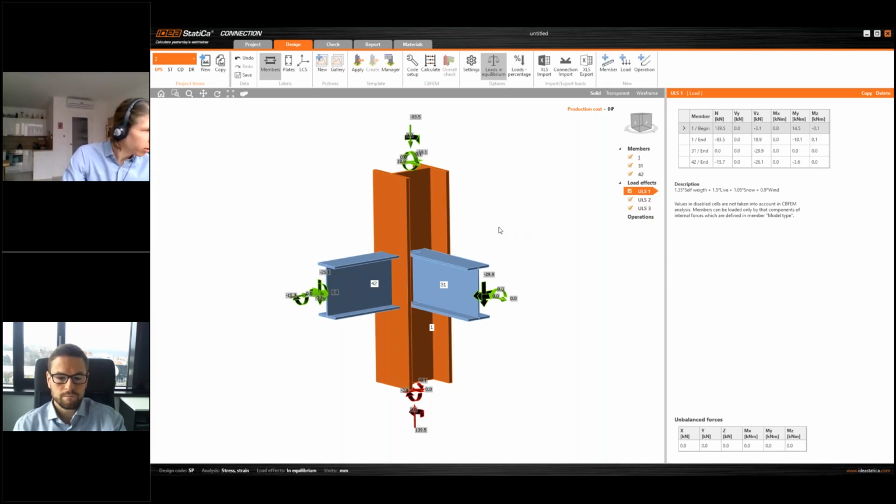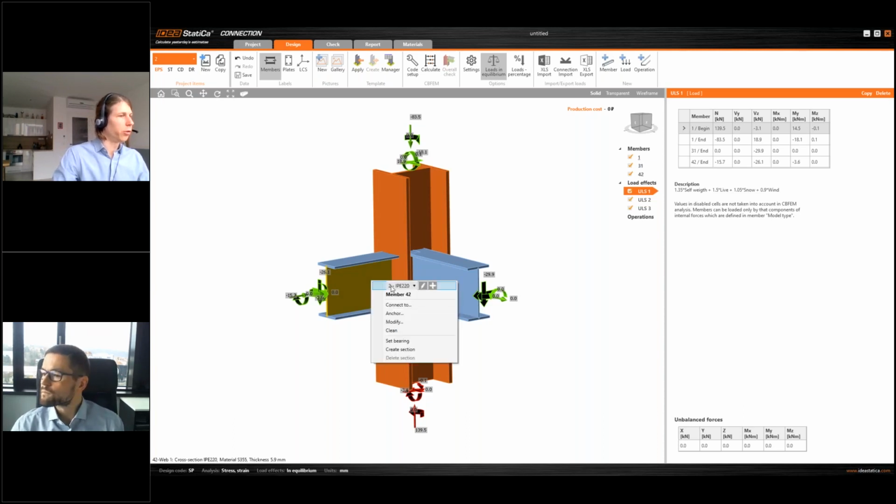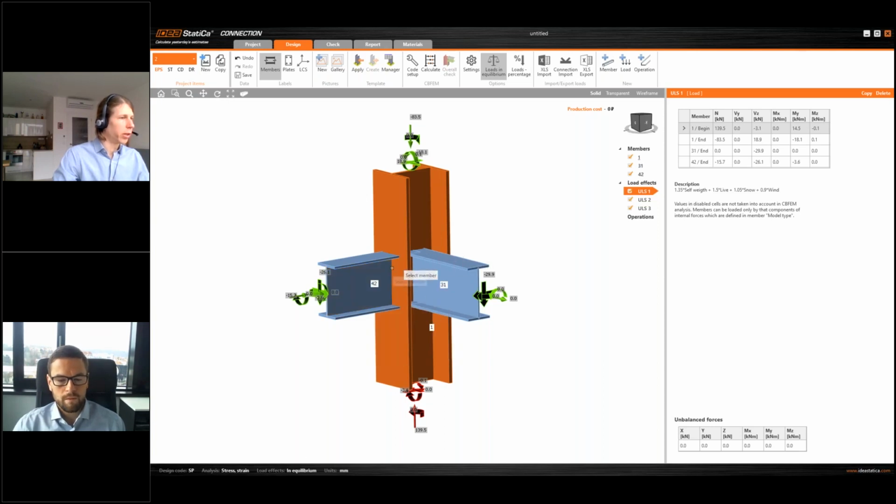And what's missing here, of course, that's different from the Tekla workflows, I don't have the connections here, right? So I have to add them. I have to do the job of designing these connections. So in this case, this is quite, let's say, a standard joint. I can use or take advantage of the right-click dynamic templates.